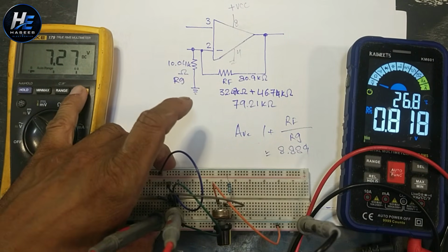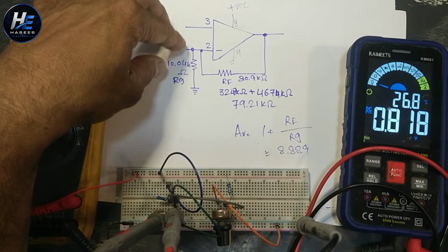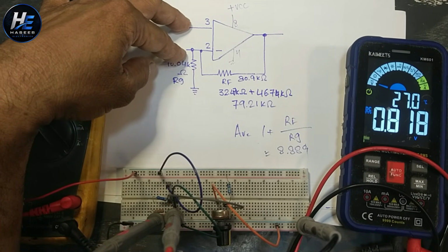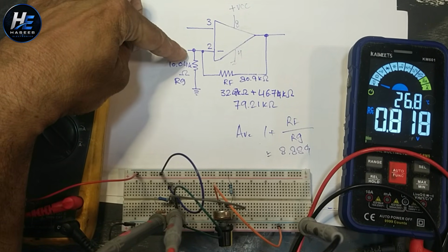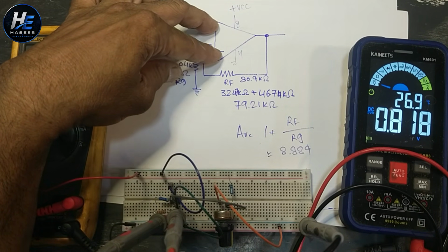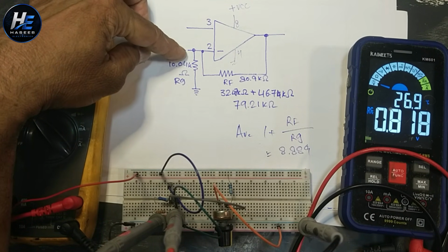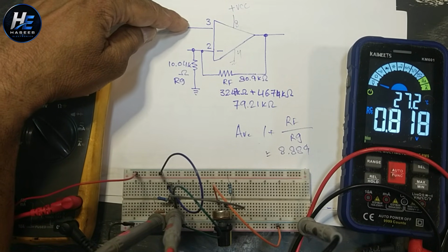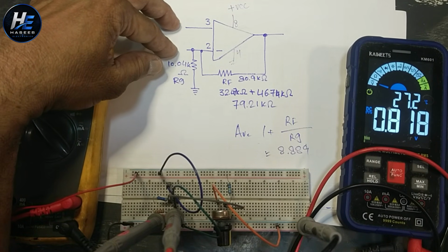There is another parameter that is called input offset. That is a few millivolt input difference by default. When we are checking data sheet, we must take care of input offset voltage. That means if it is 1 millivolt, there will be output here because of that difference due to its internal input circuit. Input offset is 7 millivolt. That means here 1 millivolt, 1 plus 7, 8 millivolt must be here. That will be considered as a 0 because that is input offset error.